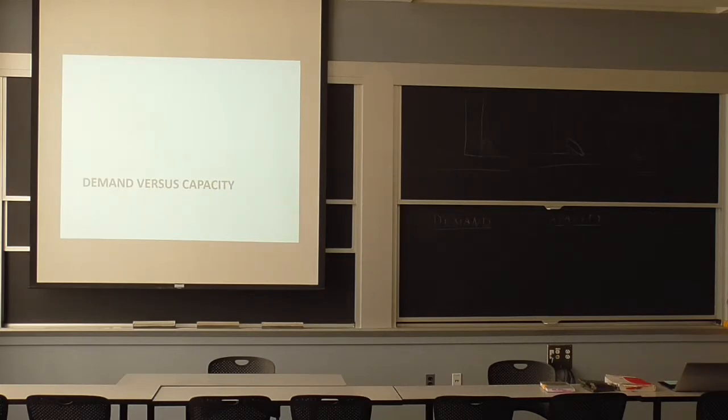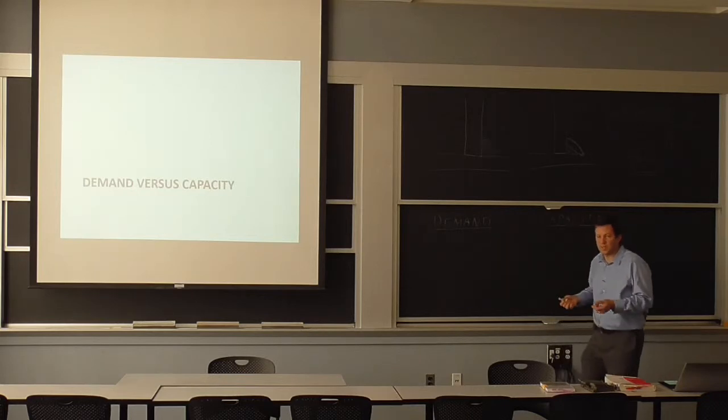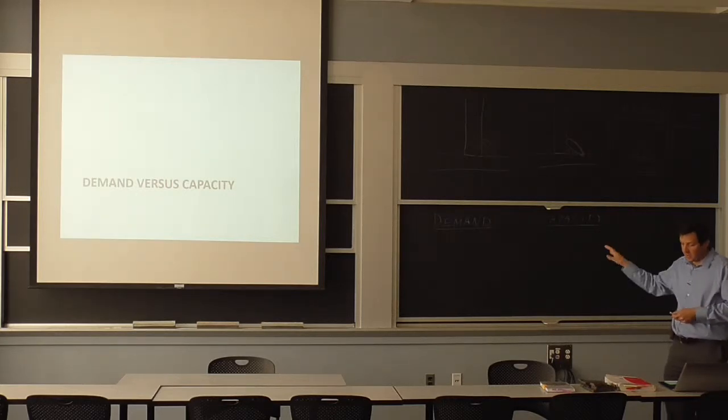properties of the materials. So for my purpose, and that may be where people differ, if we're talking about geometry, I think of it as a demand factor, because the mechanical engineer can just say, I will avoid a stress concentration factor, so I don't need a material that will be able to deform and blunt any stress concentration. So that's a little bit how I think of it, and of course there are other ways, but if we're talking about an aerospace component, that's exactly how it works.